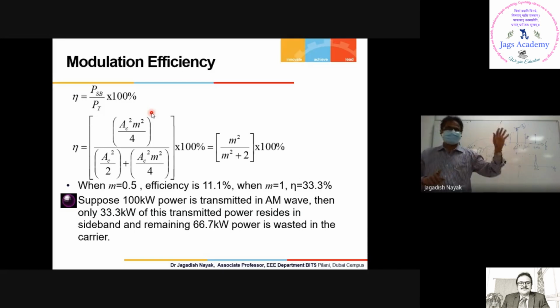First we remove the carrier. When you remove the carrier, what do you get? Double sideband suppressed carrier AM wave. Now the double sideband suppressed carrier wave has both the upper sideband and the lower sideband. Now one of the sidebands you remove. What we get is a single sideband AM wave. And how do you get a single sideband AM wave? One of the methods is filtering. There are other methods we'll discuss later.